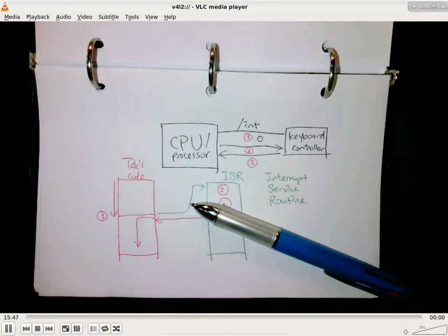The green arrow is implemented 100% in hardware. But it doesn't do it in such a way that it leaves the stack how it was when it started. So the hardware, the processor, when it handles this, is going to push a return address onto the stack. That's why. Do you know about that, the green transition, the green arrow transition? Your code doesn't know it.